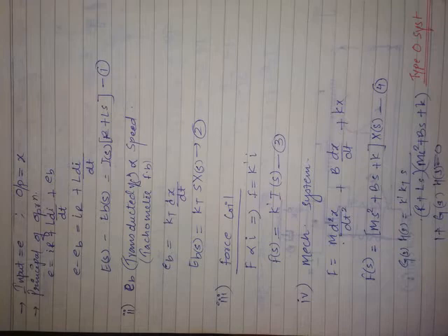Look at these equations. The overall input is present in the first equation. Because we have R minus C, the overall input is R of S. Signal to the summing point is C of S. The transfer function is KB. Output is VE of S. This VE of S is going as input to amplifier whose transfer function is KA and output is VA of S. This VA of S is going as input to armature controlled DC servo motor.